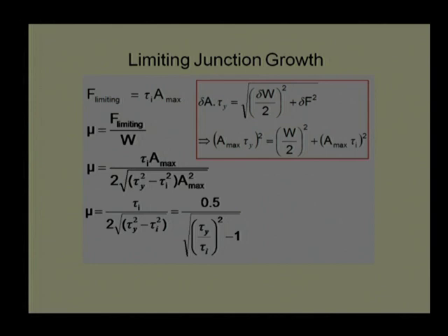If the interface is getting fractured at the value of the shear strength of the material, then the coefficient of friction will be very, very high. However, if the shear strength of the interface is very low, the coefficient of friction will be lower, and this is the reason why we provide lubricant. If we provide lubricant at the interface, the shear strength of the interface will be almost negligible compared to the solid material strength. Just to get a feel of that, we did some calculations.